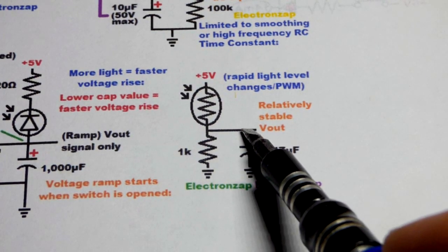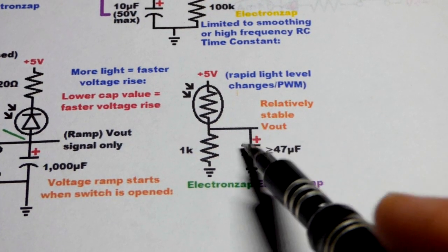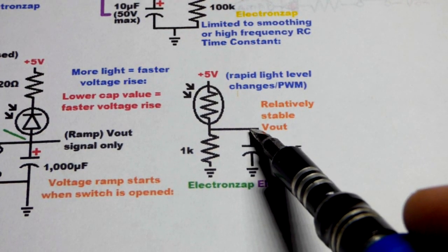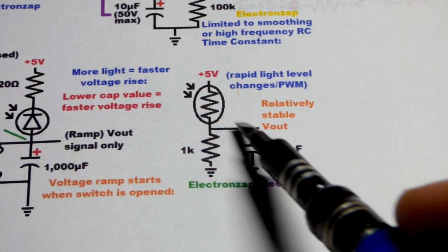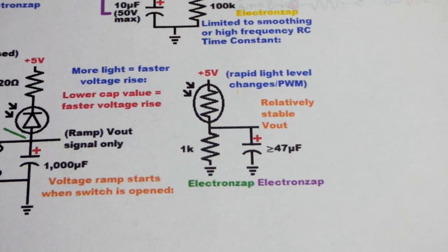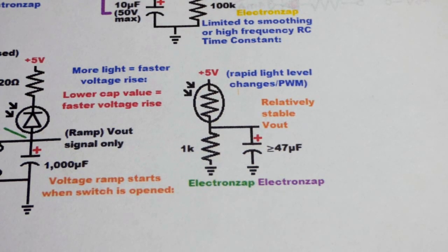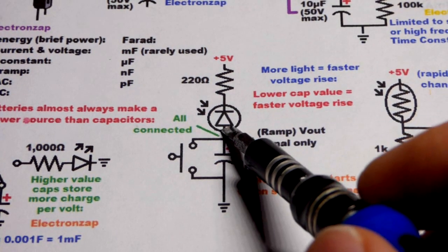So what you can do is just take your voltage divider right here, put it to a capacitor. So it may take a split second to get to the final voltage, but ultimately it will help smooth out any rapid changes right there. And you'll get a more steady voltage for other circuitry that depends on a steady voltage to keep from oscillating or something.